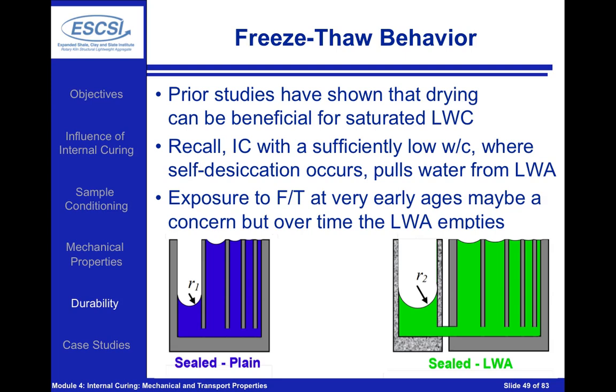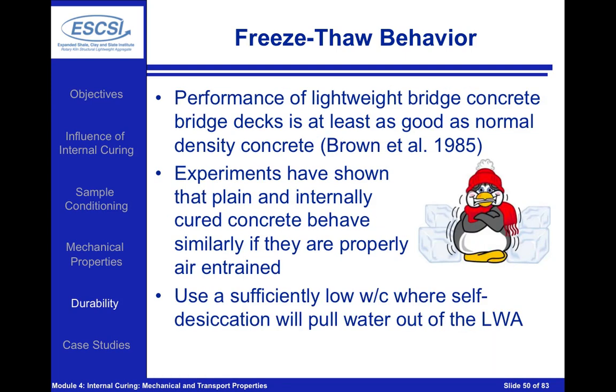Again, recall that the reason this is happening is because the water is being pulled out of the aggregates. In internally cured concretes at low water to cement ratios, 0.42 and lower, self-desiccation and chemical shrinkage are going to pull the water out of the lightweight aggregates themselves. So if we expose our concrete to freeze-thaw after, let's say, 18 or 24 hours, this is not going to be a typical concern any more than we would have in a normal conventional concrete, because the water is being pulled out of the lightweight aggregate the same way we would have seen this with drying in a much more conventional concrete.